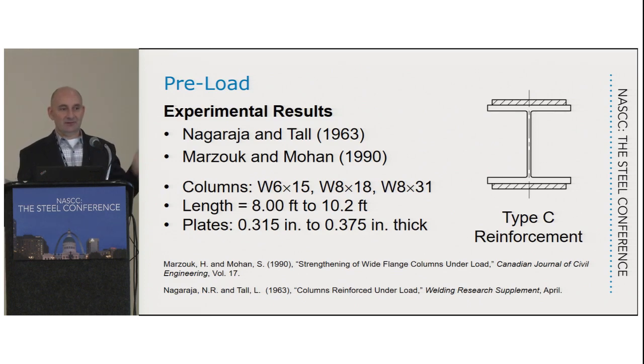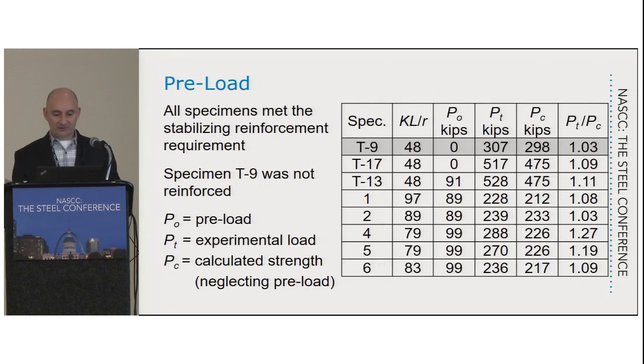And so that's the theoretical explanation for the 6% increase between those two specimens, because it's going to yield at a higher load if you have the tension residual stresses, and when it yields, it loses the stiffness, the resistance to buckling. Okay, so that was pretty interesting, but this one is even more interesting, and I do not have a theoretical explanation for this one. T13, we put a preload.